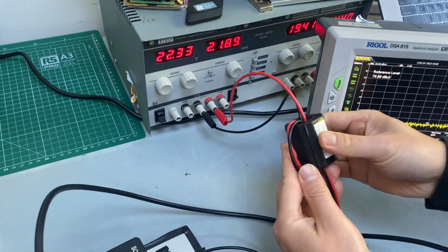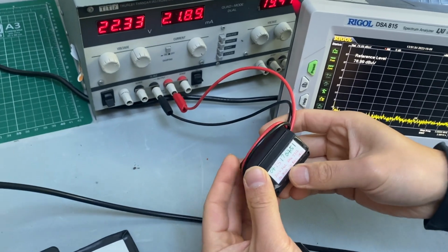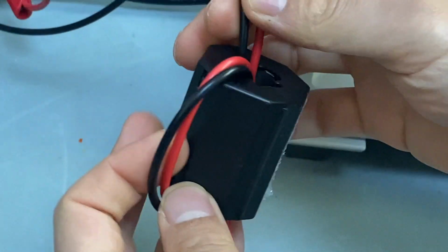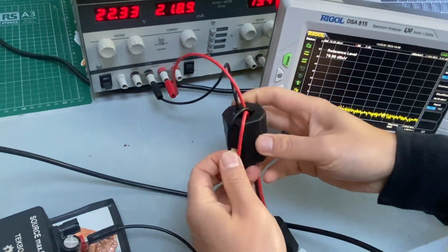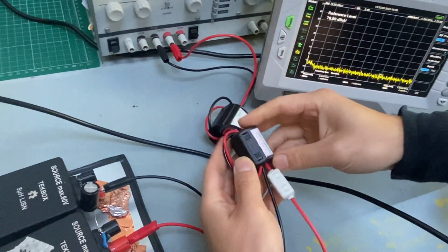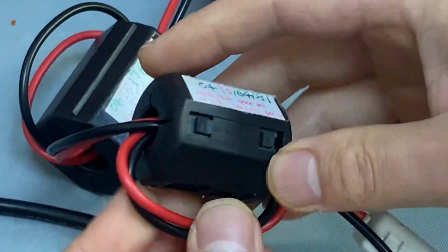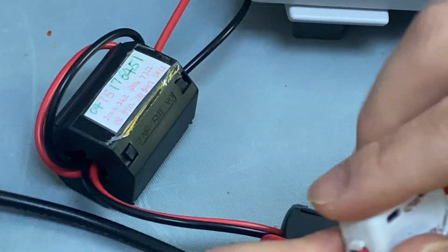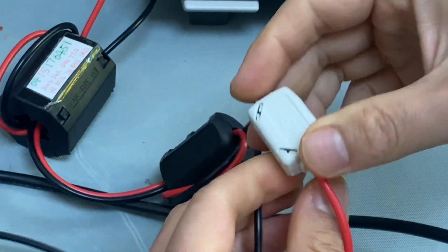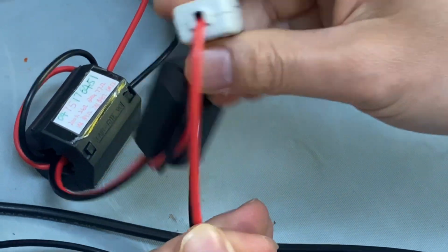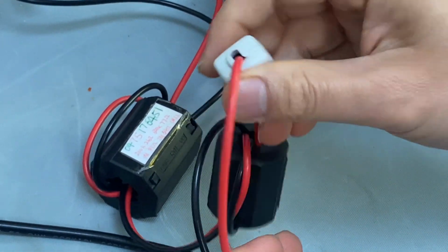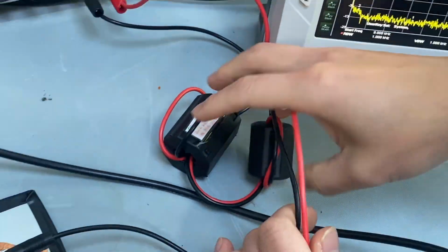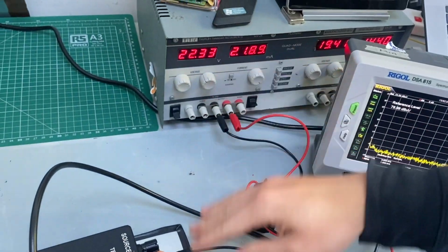This ferrite is 75 material, often very effective in the 1 megahertz to 2 megahertz range. I wound it in a 2-turn common mode configuration, okay? And then this is, again, 75 material ferrite, again in a 2-turn common mode configuration. And then this one is a small ferrite only on the live, or low voltage, power line here, right? So why do we need these ferrites between the power supply unit and the LISN?